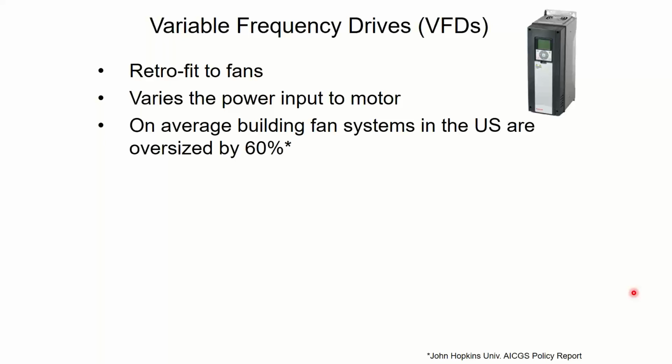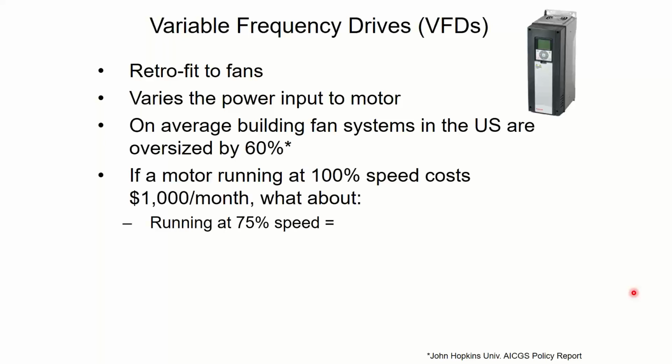I know at a lot of places, a lot of manufacturers of rooftops will sell a low static fan, a medium static, and a high static. Almost every distributor I know always stocks the medium static fan because then they figure, well, I'm right most of the time, right? It's kind of in the middle. If I pick the low one, then I can't help somebody who needs high static. So a lot of these buildings get this medium static fan, even though the vast majority only need the low one. But that's what they do just to kind of minimize their stock.